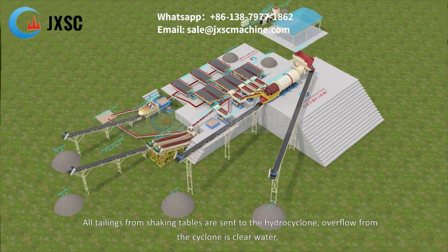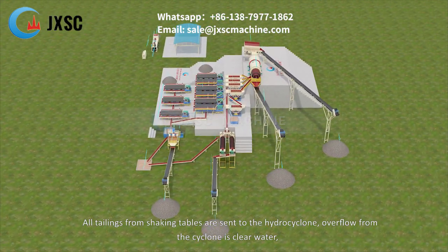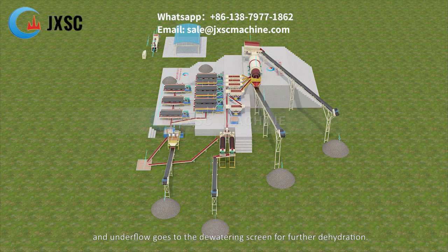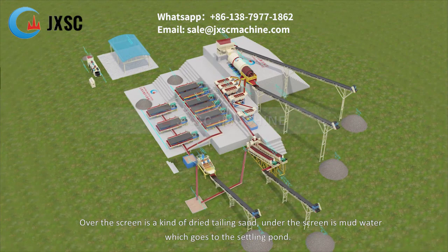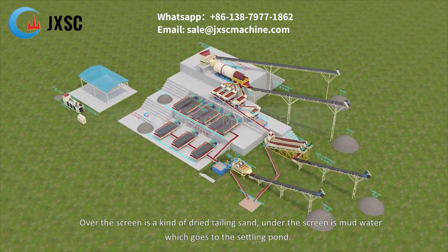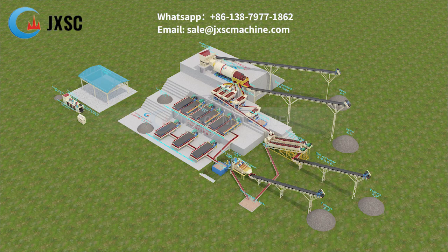All tailings from shaking tables are sent to the hydrocyclone. Overflow from the cyclone is clear water, and underflow goes to the dewatering screen for further dehydration. Over the screen is a kind of dried tailing sand. Under the screen is mudwater, which goes to the settling pond.